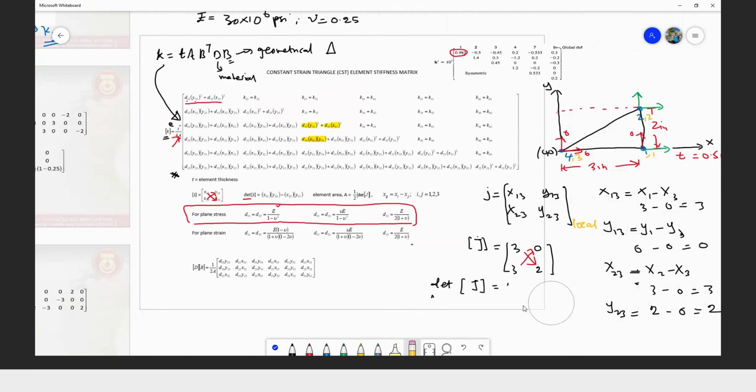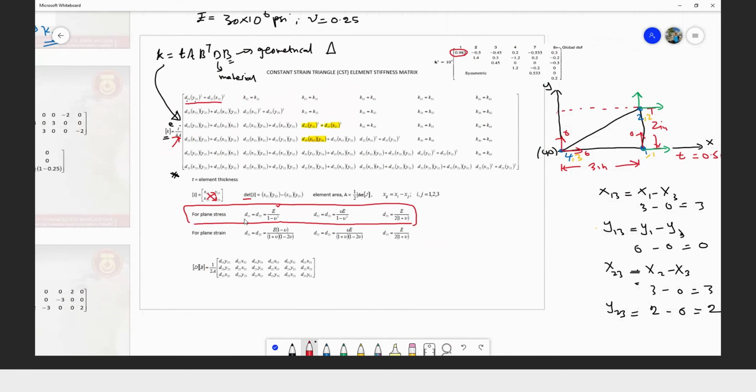I don't have much space here. Otherwise, if I zoom out, it will probably be hard for you to see the font. So I have to remove some of this. What you need to do is prepare D11, D12, D33, because this information will be used in some places within your K matrix.